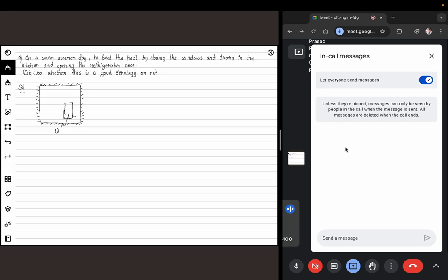In the event that it is well insulated from the surroundings, let's say your doors and windows are completely closed, and all your walls are highly insulating so that you do not have any heat transfer from the internal to the external environment, in that scenario your Q will be 0. Now, if you apply the first law, it tells you that delta U plus W should be 0 since Q is 0, so delta U is minus W. In this particular case, we are connecting the refrigerator to an electrical supply, from which work is being done on the system. My system is this entire room.